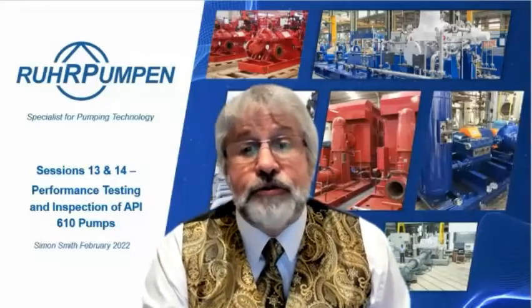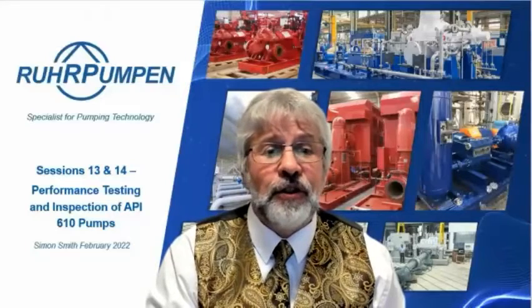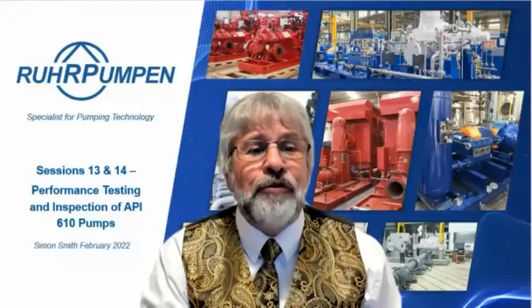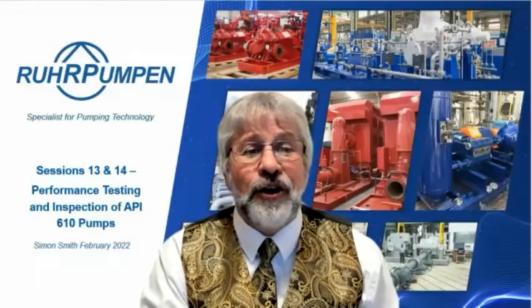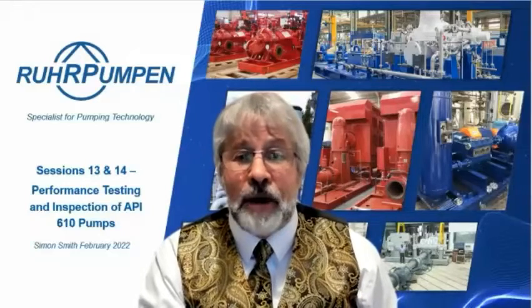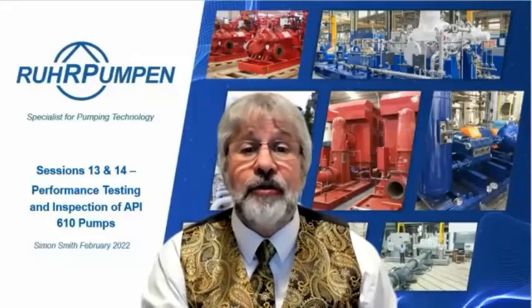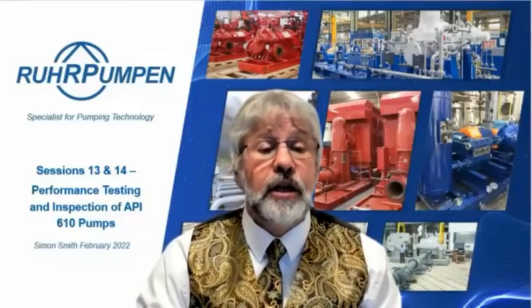The mechanical run test of 4 hours is independent of what the temperature of the oil is. If you ask for a mechanical run test until the oil temperature is stable, the pump vendors are going to charge you probably for a 4-hour test, and it'll be the same if you just ask for a 4-hour mechanical run test. It'll be the same price, I would imagine.